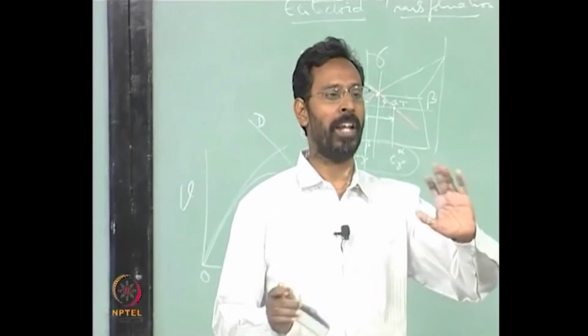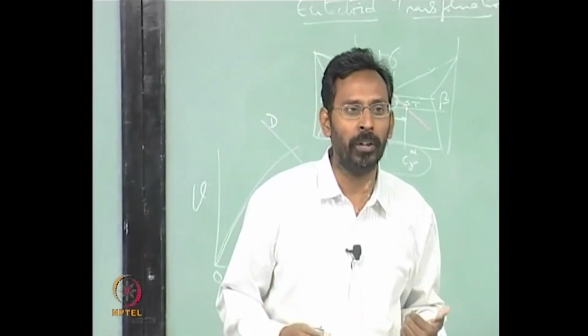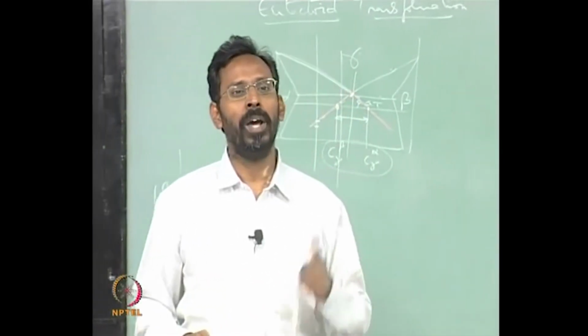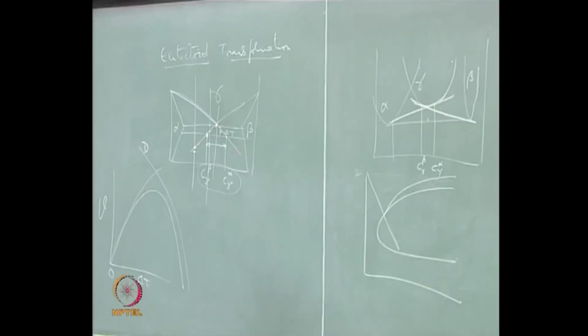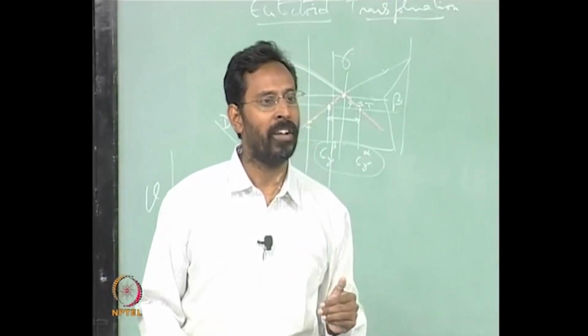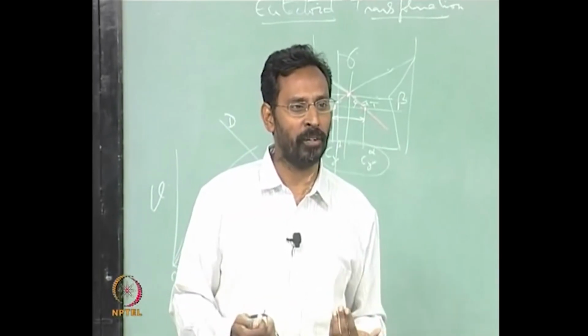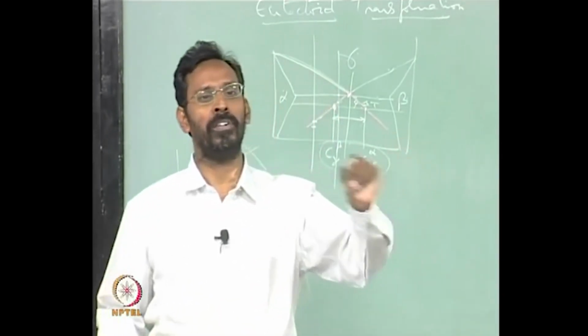In principle, if it is a plain carbon steel, we can do this provided we have an annealed microstructure. If you have a normalized microstructure, it will not represent the composition of the alloy, basically because you are going to use the lever rule and from the lever rule find out the composition of the alloy.